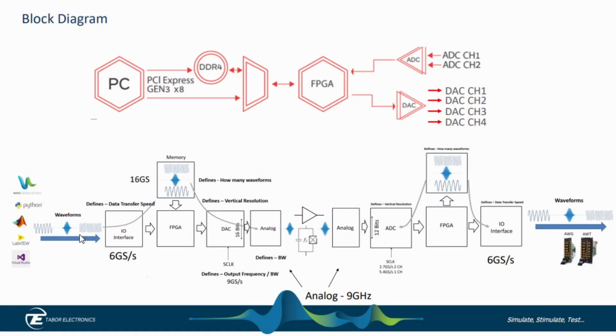So far we've looked at the arbitrary waveform generation section. We focused on the DAC. We learned about interpolation, we learned about multiple Nyquist zone operations, and we learned about the IQ modulator. Then we went over to the high-speed digitizer section. We focused on the ADC. We used the ADC in multiple Nyquist zones all the way up to X-band. And what we're going to do now is look at the real-time waveform streaming.